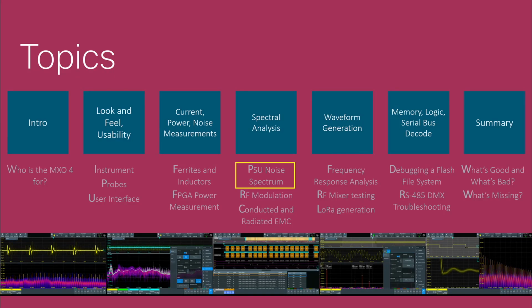The spectral analysis is very essential for modern scopes, and especially high resolution ones, because it's impossible to make maximum use of the high resolution from time domain views. The spectrum view is used to pull out signals that can't be seen in the time domain signal representation, regardless of how much the signal is zoomed in.